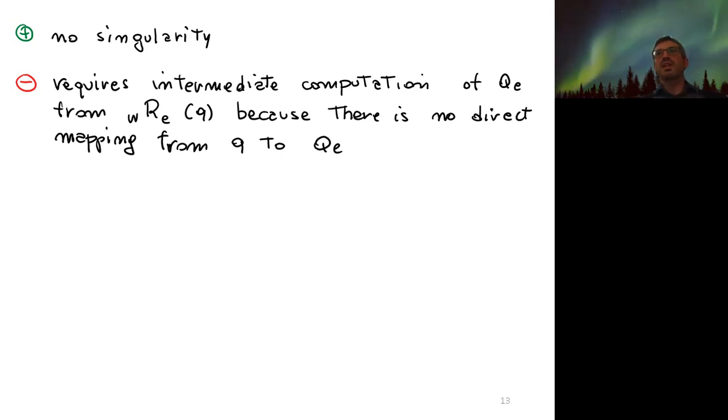So in the case of the desired quaternion, you compute it just once, while for the actual one, you need to continuously compute it while the end effector is moving, according to the actual orientation that is changing with the joint positions.